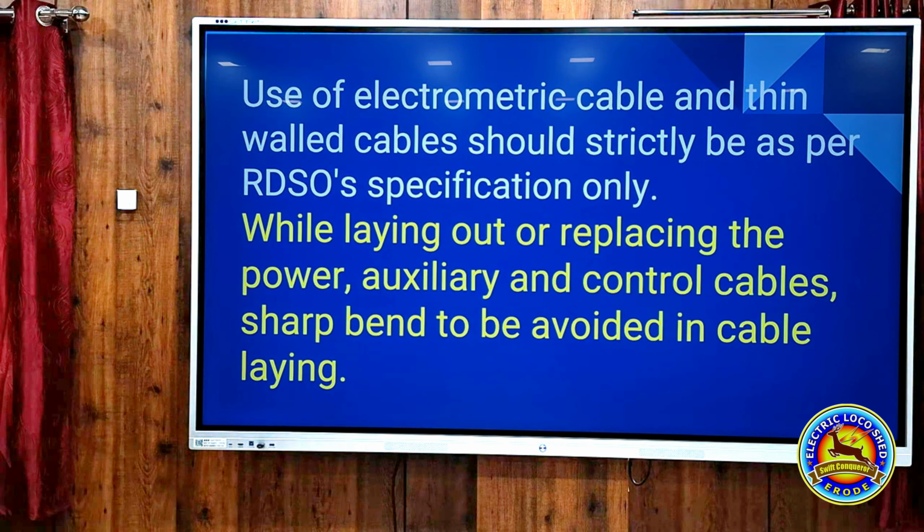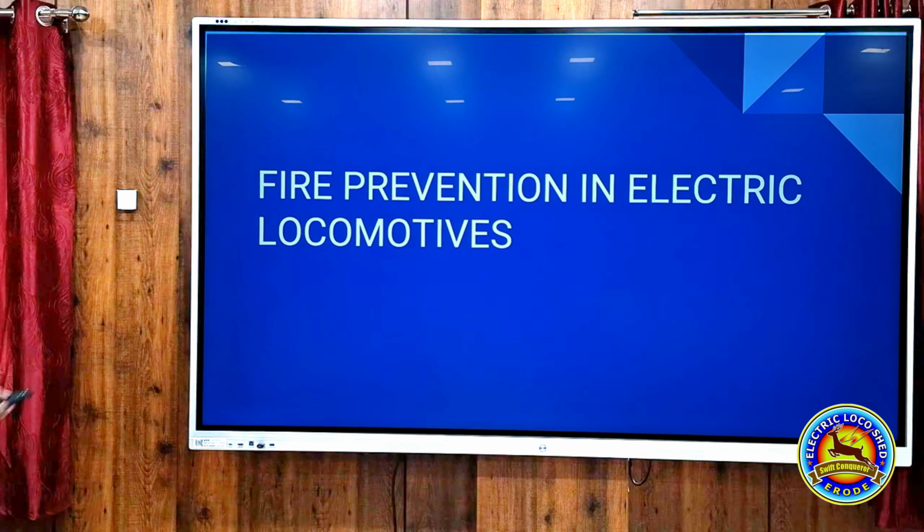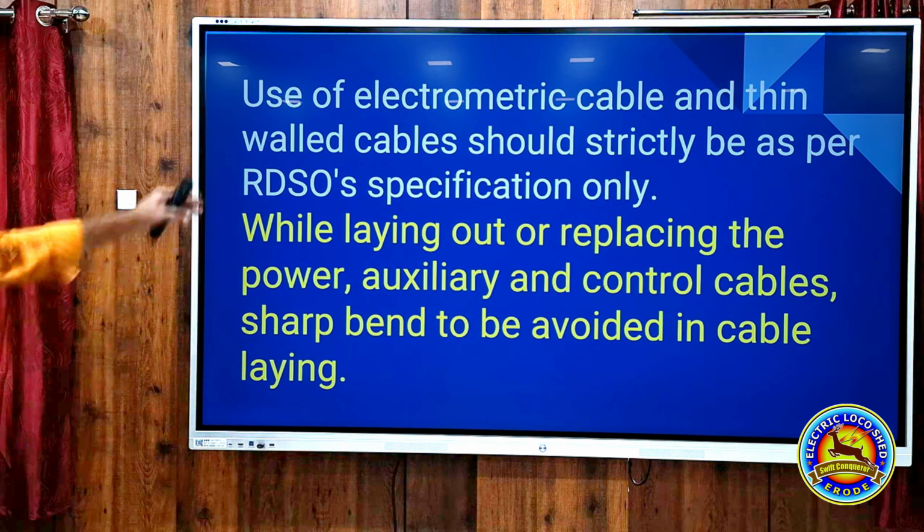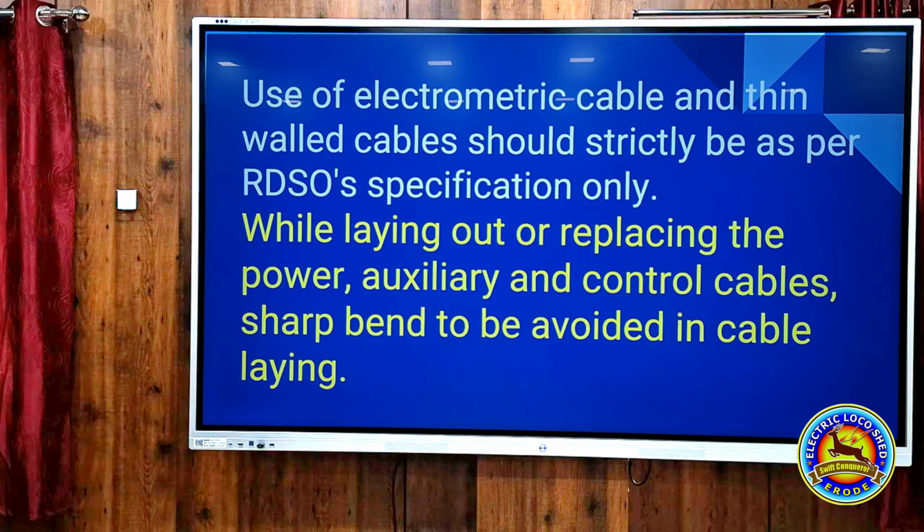This is from the letter from 2006. Use of elastomeric cable and thin-walled cable should be strictly as per RDSO specification only. We have to use RDSO specified cables only. We should not purchase any local market cables.